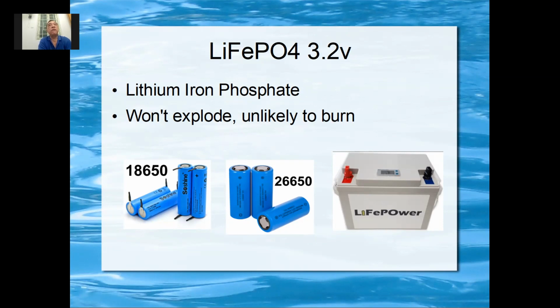Then when it comes to 48 volt, normally you take a lead acid battery or AGM battery or deep cycle battery, all these are lead acid battery. You need 48 volt, they will take the 12 volt, they put 4 pieces of 12 volt together, then they get 48 volt. Okay, but in lithium battery, you normally should not connect them in series.